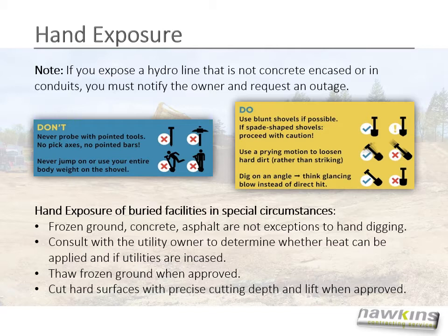First of all, don't probe with pointed tools. Don't use pickaxes or pointed bars, and never jump or use your entire body weight on the shovel. But do use blunt shovels if possible. If your shovel is spade-shaped, proceed with caution. Use a prying motion to loosen hard dirt rather than striking. Dig on an angle. Think glancing blow instead of direct hit.